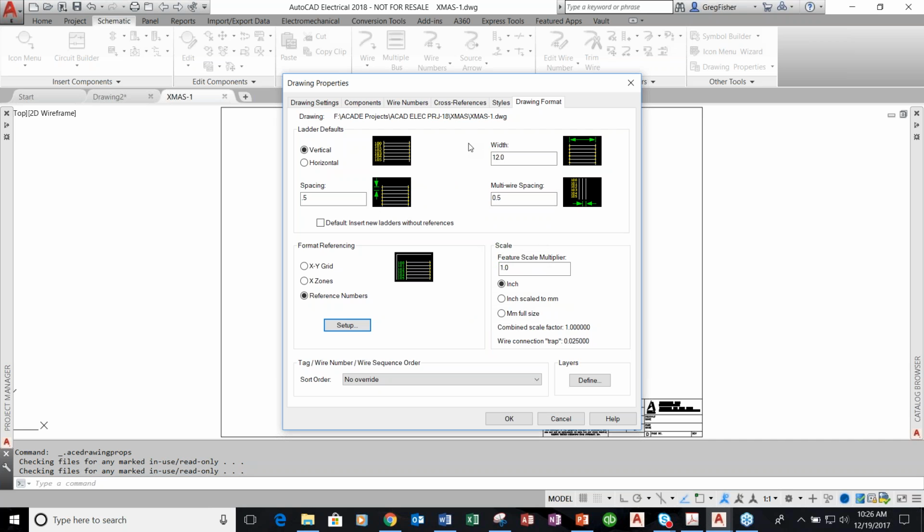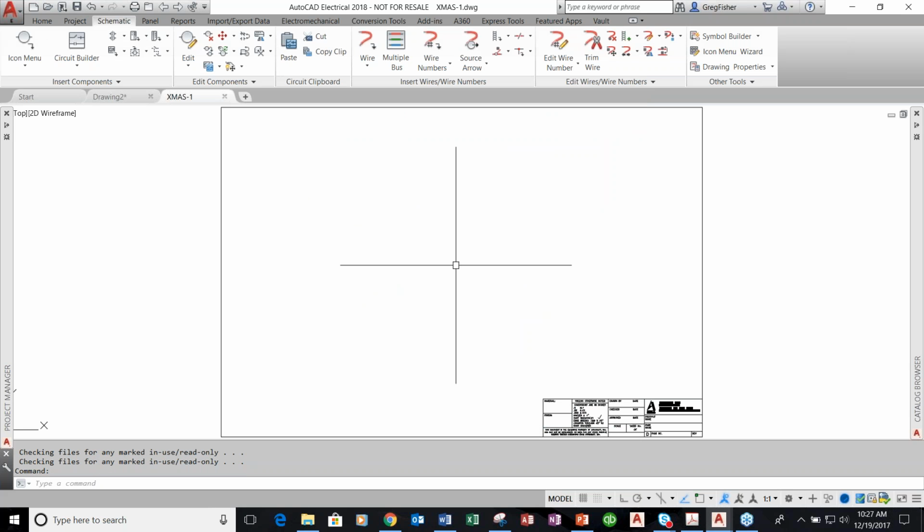You want to design circuits and attach part numbers to symbols. You don't want to be messing with properties. That's why it's so important that you build them into the template file itself and the template project itself. Now, we're going to move over to the title block setup at this point.